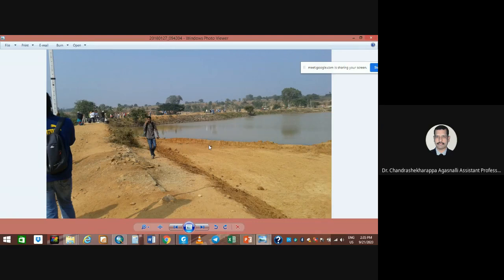And for water supply and also for high rise pipelines, for better practice we use the compass as well as the chain survey. Really, we are not going for the chain survey because carrying it is a problem, so we used to take tape and compass surveys.